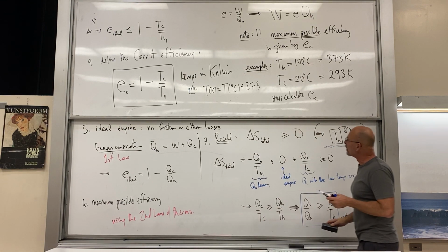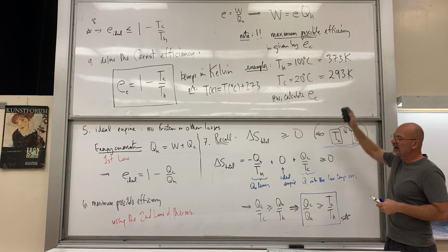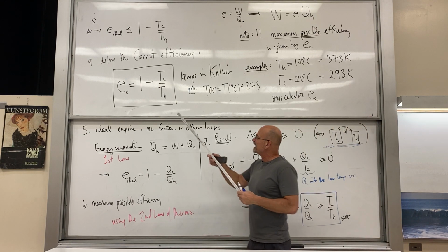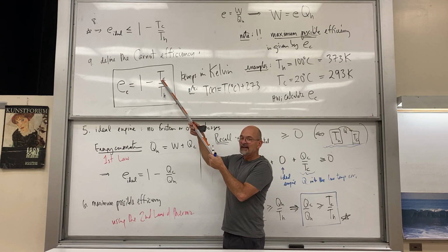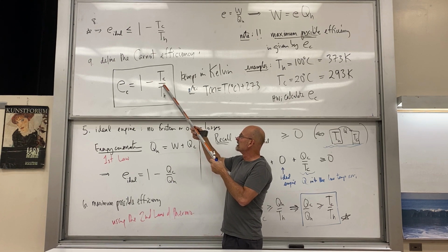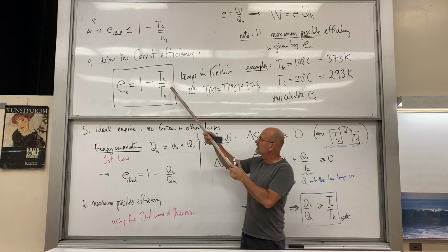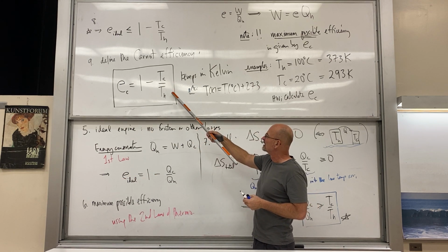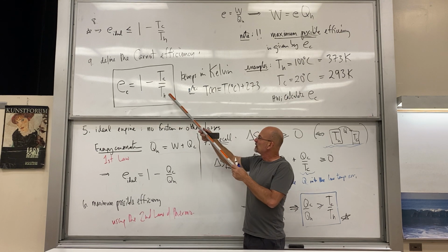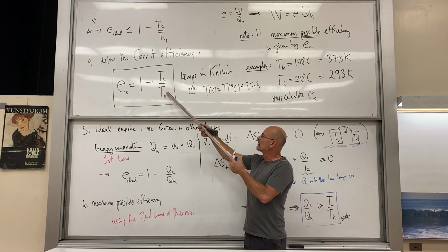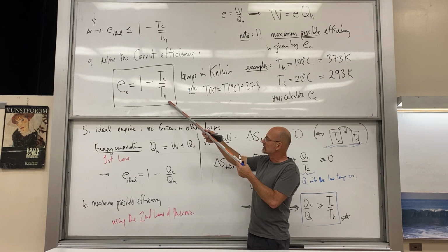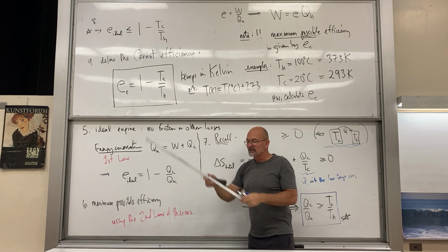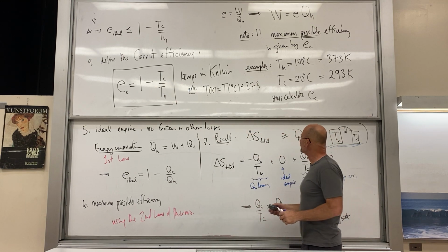And I'll give a second homework problem, because you're saying, well, 20% is not that efficient. Okay, so how can I get a higher efficiency? It's difficult to get the Tc to be low, because in fact the machine heats up and the Tc is actually going to be a lot hotter than the outdoor temperature, because the machine itself is hot. So what one has to do is have very high temperatures, very large TH, and you have to have means of releasing as much heat as possible.